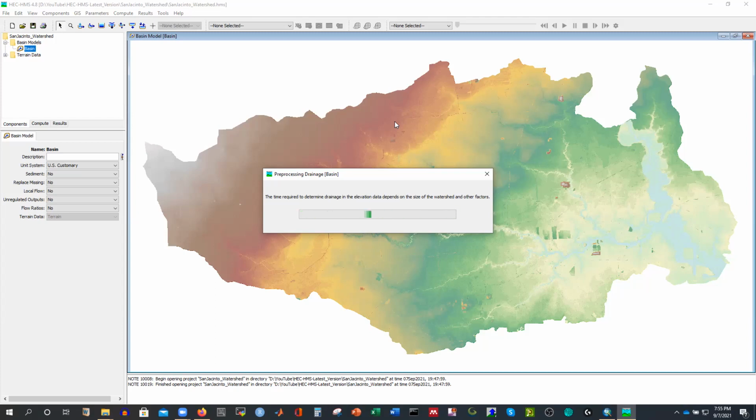And if you want to run the model for a long time, for example 20 years, because I ran the model for 25 years, the same HEC-HMS model for another watershed in Texas, and it was a lumped model. What I did was select the loss method as soil moisture accounting, rather than the curve number method or even the deficit and constant method.